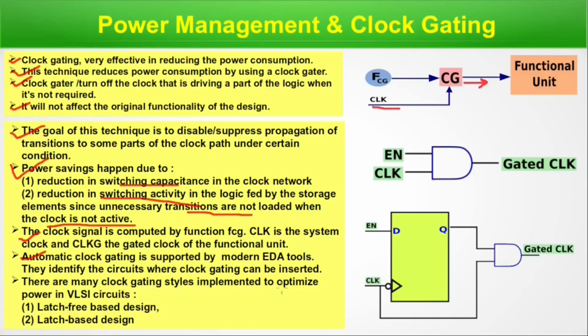There are many clock gating styles implemented to optimize power in VLSI circuit: latch-free based design and latch-based design. This is a latch-based design and this is latch-free based design. It's an AND gate. Enable is here, clock is here. That is the gated clock. And that is enable is going inside, the clock is here, and this is gated clock. So it is latch-free, that is AND gate based, and that is latch-based design. This is deep clock. Not only gated clock, the latching property is used here. We will see it later in details. So we are done with this slide. We will move to the next slide.